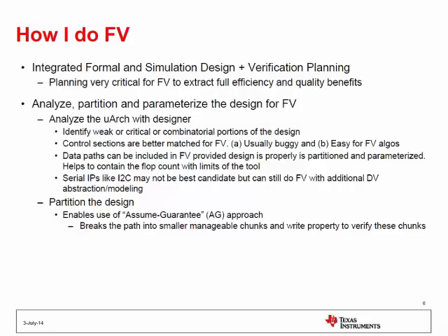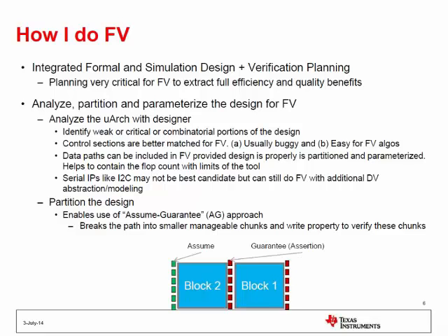I think the partition thing I want to mention, as I was saying, is that if you partition your design, then you can make your assertions use the assume-guarantee approach they usually talk about. Once you apply it on one block and you interface with the next block, whatever you used as an assume in the previous design now becomes your assertion. And you'll have a common set of things, whether at one IP to another IP, where you see certain assumes becoming a property. So this is actually a very useful method, which enables you to split complex properties and also to manage your whole runtimes and stuff like that.